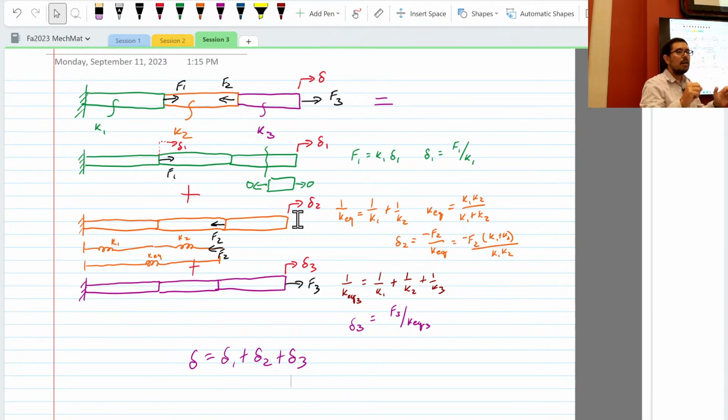Deformation is dependent on internal force. Yes, we often think of reaction and action pairs, and we think, oh, I'm pulling by this amount, and there's no reaction down there, so I know I'm stretching it by that. In reality, what we care about is the internal force. If the internal force is constant across it, then that's what we use for the deformation of that member. It just so happens that the internal force is often equal to the external forces being applied.